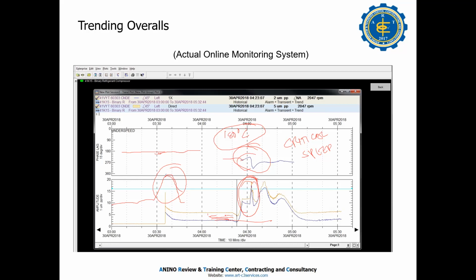Then if you pass by the critical speed, you must go higher, maybe 25 meters per second, because if you stay steady at the critical speed, the vibration becomes higher. So why stay at the critical speed? Just pass directly by.